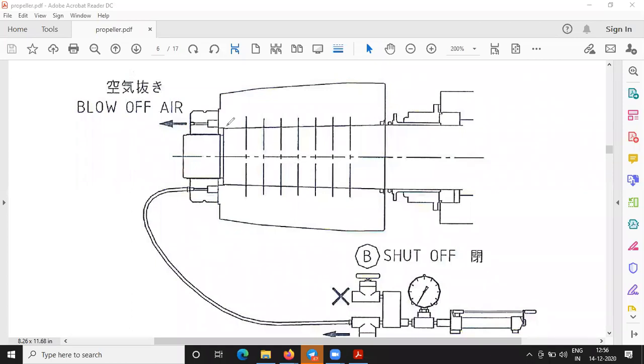In the dry method, what will you come to know? You will come to know whether the propeller boss is properly aligned with the shaft or not. And you will come to know whether the apparatus which is fitted is proper or not, whether the surfaces are cleared for smooth running. That means the surfaces have to be smooth, both on the tail shaft as well as on the inner surface of the propeller boss. All those things have to be taken into consideration. First, we'll start fitting it. Then if anybody has any doubts, please do ask, because it's very important to clarify your doubts.